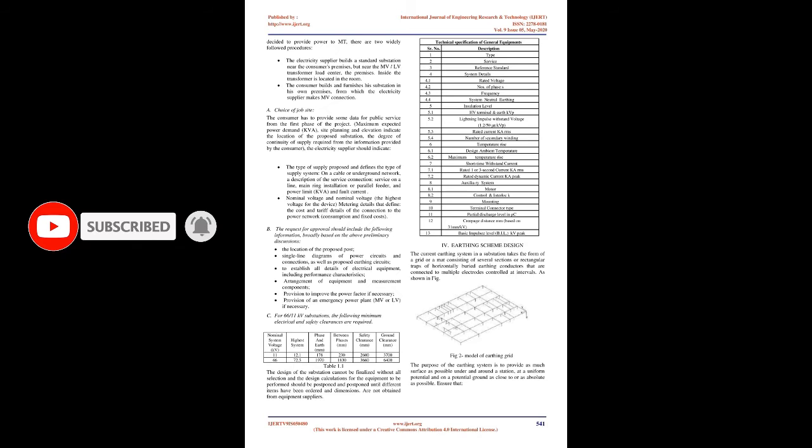B. The request for approval should include the following information, broadly based on the above preliminary discussions. The location of the proposed substation. Single line diagrams of power circuits and connections, as well as proposed earthing circuits. All details of electrical equipment, including performance characteristics. Arrangement of equipment and measurement components. Provision to improve the power factor if necessary. Provision of an emergency power plant, MV or LV, if necessary.